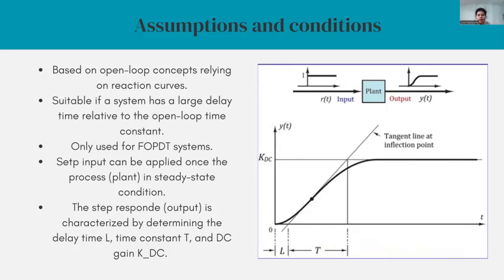Second, the method relies on step response analysis. The step input should only be applied after the system has reached a steady state to ensure accurate measurements. Additionally, the method assumes that the process is linear and self-regulating, meaning it settles naturally without external intervention.